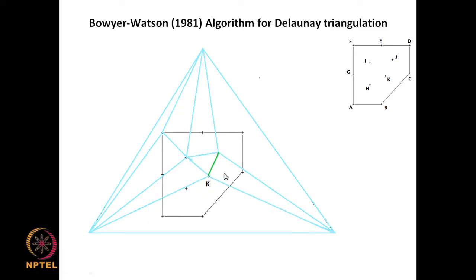So, this is what we mean by applying that Delaunay triangulation criterion. Okay. So, we can see that we have created 2 triangles here with a total net aspect ratio which is smaller than if we were to join like this. Now, if you take this quadrilateral, again you can see you have the option of joining like this or like this, and this is obviously the better option. If you take any other quadrilateral, you will see that that is the case.